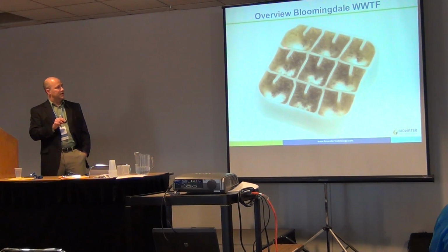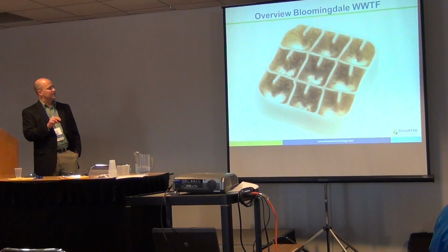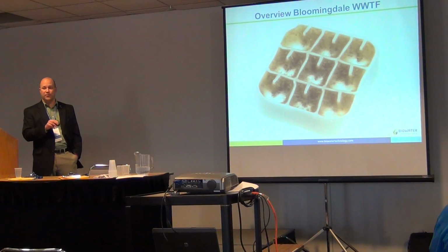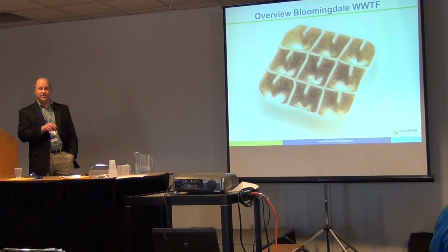This one here is made for heterotrophic growth with BOD reduction, and the openings here are pretty large. And heterotrophic growth has very thick biomass growth. You can get anywhere from 10 to 20 grams of biomass per square meter. If we were looking at a nitrification stage, and only nitrification, we would probably use a different style media where these pores here actually get smaller and you can fit more of them.